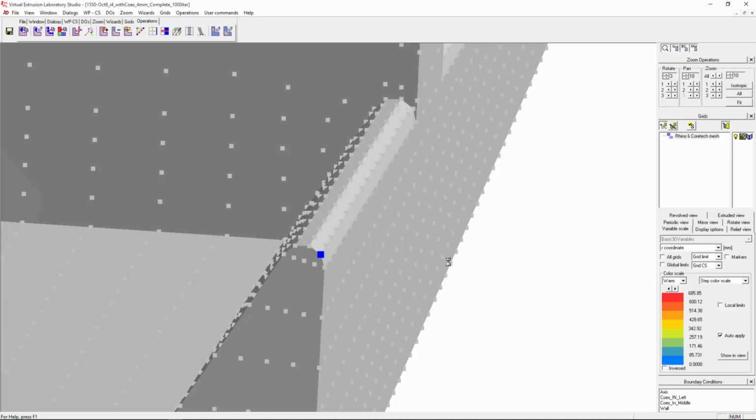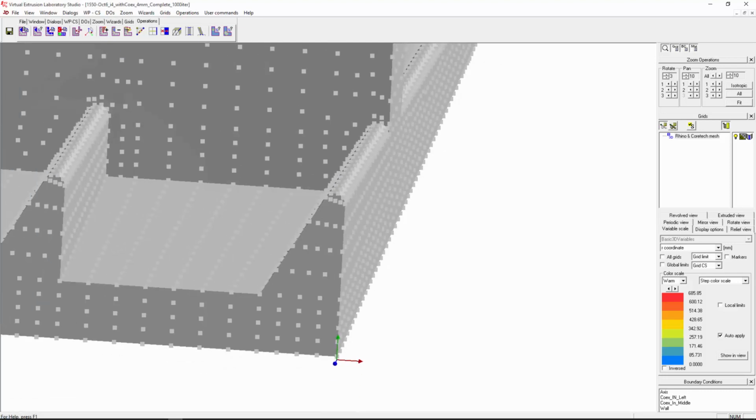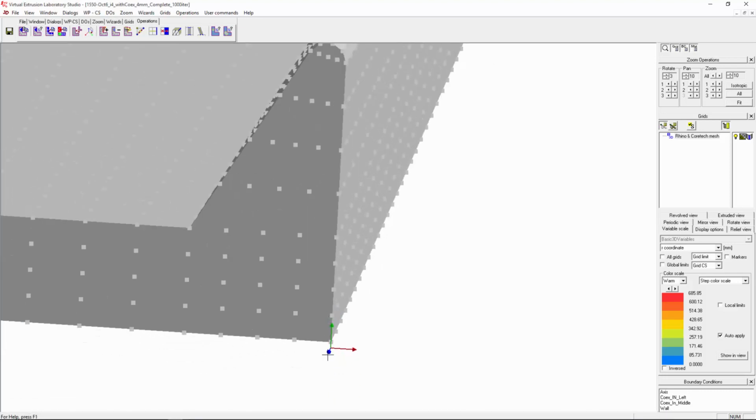So that's why we have here a command align. So I can align entities. Now, to which axis? This is very important because the command is dangerous. We want to align to the YZ axis, right? So we just say align YZ. And now I don't put 0.03, that would be too risky, but I can put 0.01. This is 0.01 in this direction and 0.01 in that direction. So our nearest point is 0.03 minus, so that is less. So this point remains, but these ones which are like minus 0.006 will be aligned.